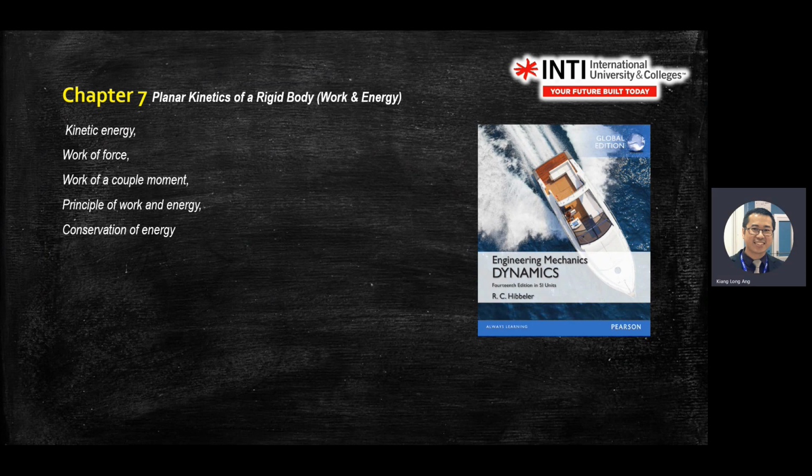So that is how you find kinetic energy, still using half mv squared. Then potential is mgh. But now in chapter 7, you should give yourself a datum already. Datum will not be given. You should say, I refer to this point, this level, as my datum. Above datum is positive potential, below datum is negative potential.